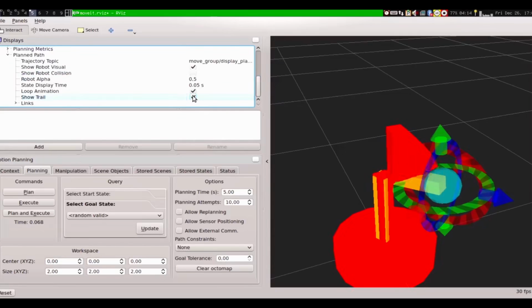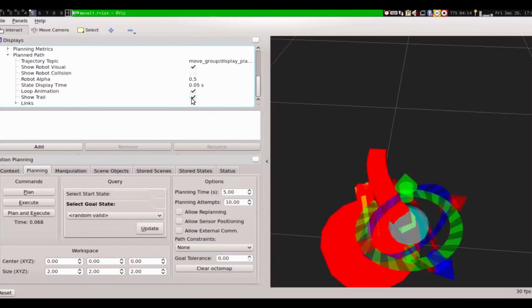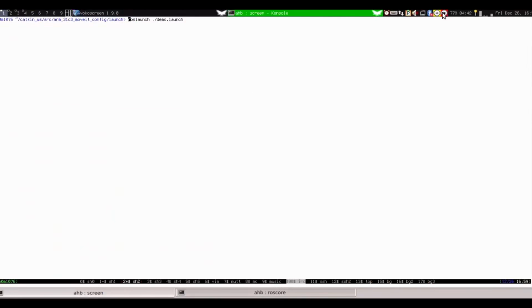It's very, very counterintuitive what these joints are doing in order for the robot to simply move along a straight line in our Cartesian 3-dimensional space. And here you get it out of the box. And the nice thing is, this is now just a dummy robot, but if you would connect your servo motors to a controller, do some low-level setup so that you can specify what number do I have to send where so that your servo moves into this position, you can immediately use this GUI to move your real robot, to do path planning with your real robot, and you can even put a Kinect next to your robot and do collision-free path planning using the MoveIt framework.